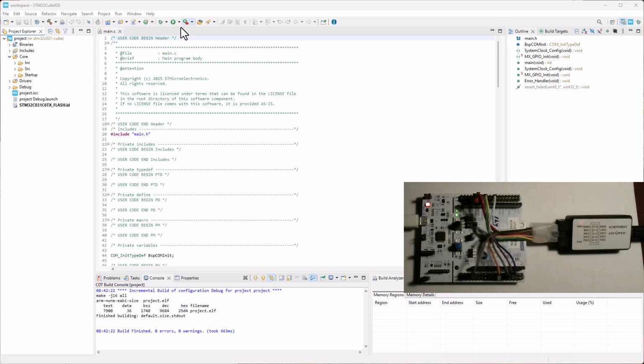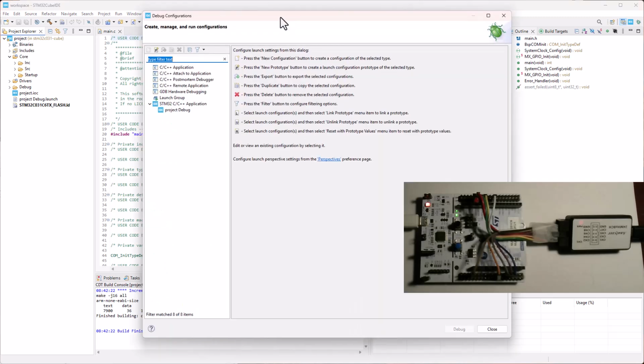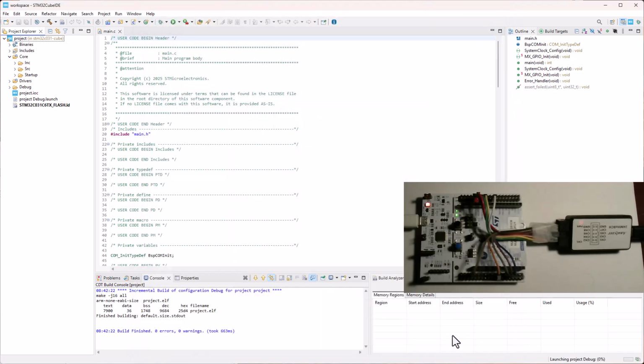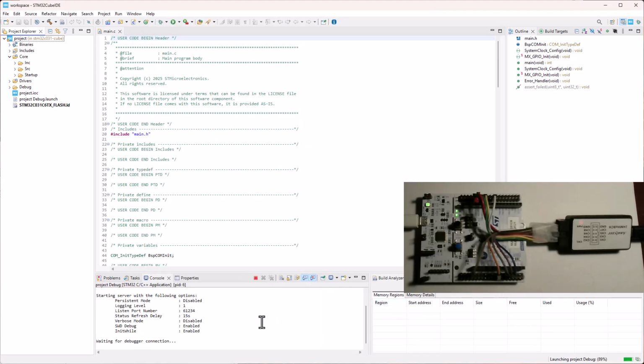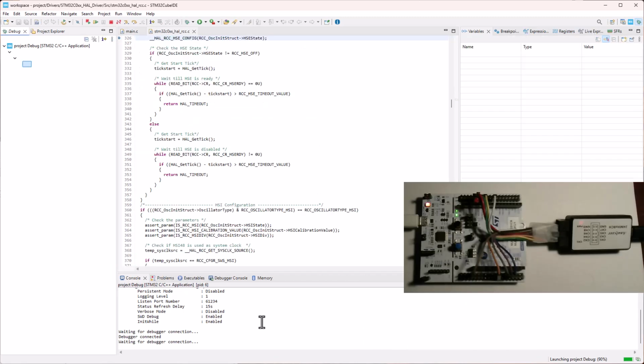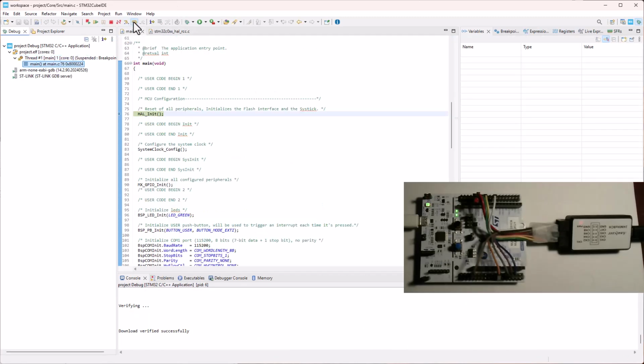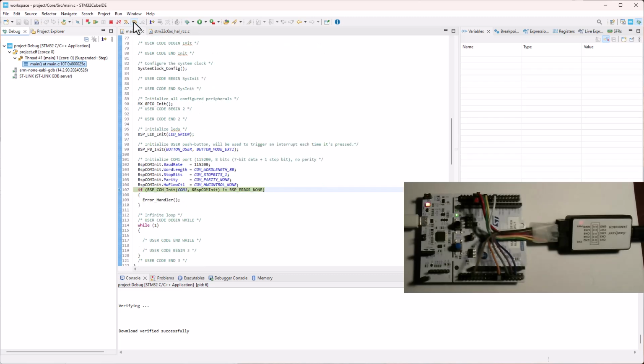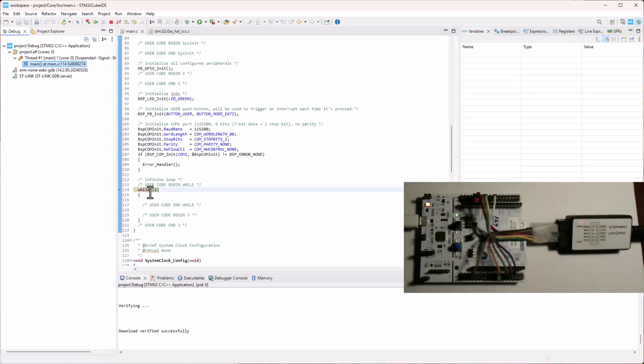The build should succeed and should create the debug directory on the disk. Alright, time to connect the NUCLEO C031C6 board to your computer and debug the code. If you are running the debugger for the first time, you might need to make sure that the Eclipse debug configuration is available. Once the debugger launches and connects to the board, you can step through the code up to the obligatory while(1) superloop. However, the superloop is empty, so nothing visible happens even though the code runs correctly. So far, so good.